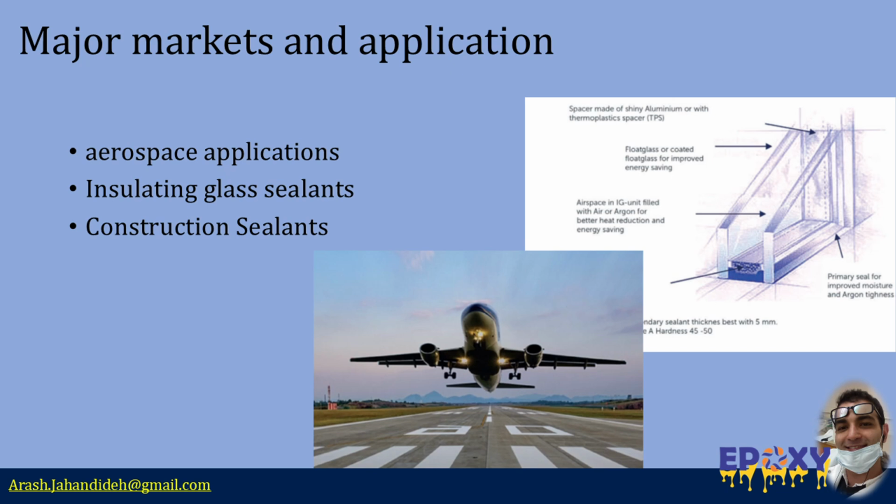In the construction industry, liquid polysulfide-based sealants are commonly used to bond glass to aluminum frames, fill movement joints in concrete, seal between steel and stone elements, and more. These materials are especially valuable in structures that must withstand long-term water immersion or persistent exposure to high humidity, conditions that typically challenge organic sealant systems.